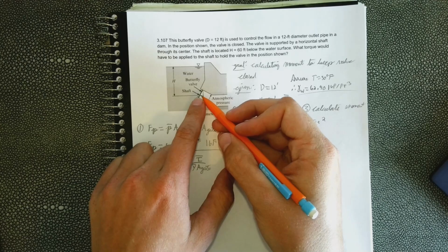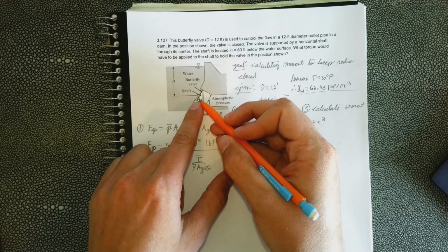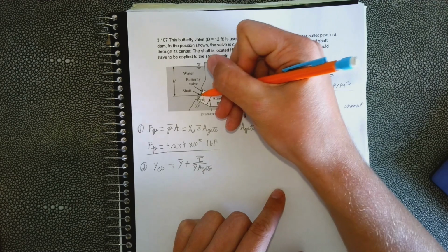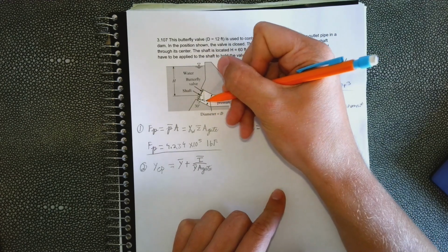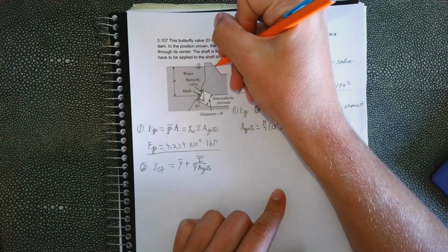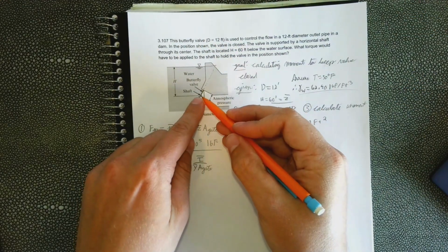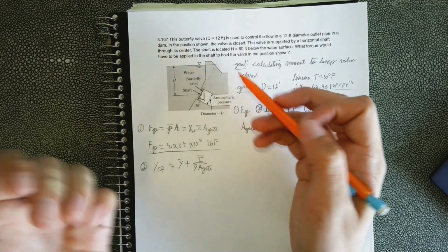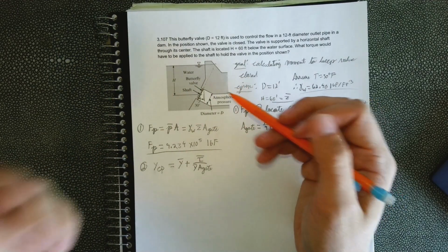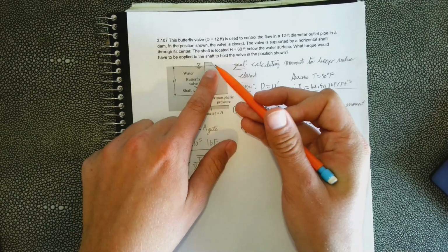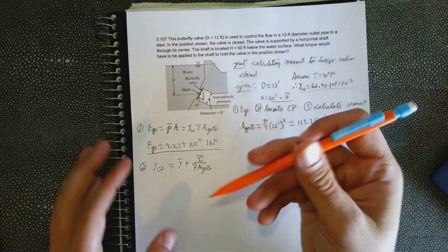So the centroid is where the shaft is. The center of pressure is going to be a little bit below it. So we know in this, when it says slant distance, it just continues on this 30-degree vertical angle all the way to the surface. So from this dot at that 30-degree angle to the surface of water, that's the slant distance of the centroid. And same thing with the center of pressure, but it's just from here to the surface at that same angle.